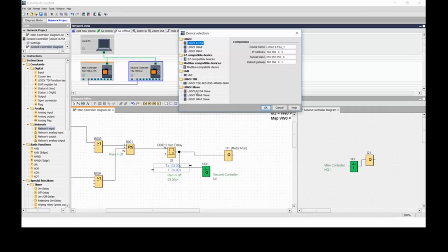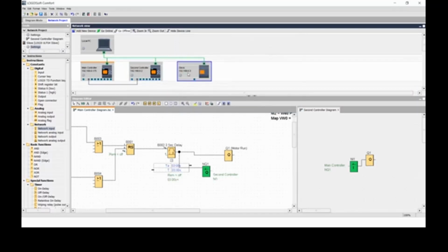We can have a look down our hardware catalog and see we've got a folder of slaves at the bottom. We'll pick the latest one in the list because that's the latest version. I'm going to give it the name slave. I'm okay with the IP address. Again, I'm just going to drop that gateway out and click OK. So you can again see it's dropped the device in. It looks slightly different though.